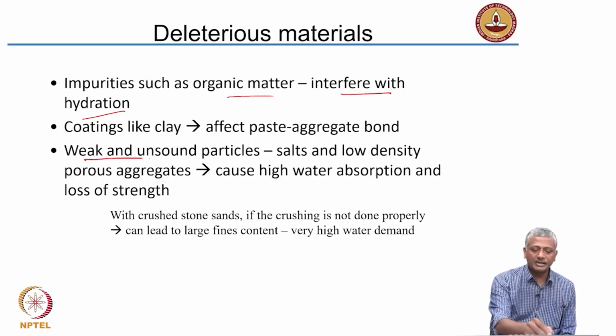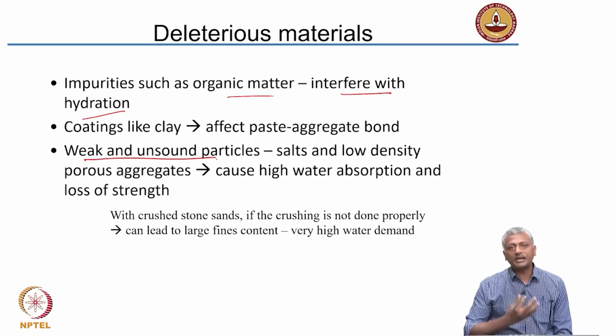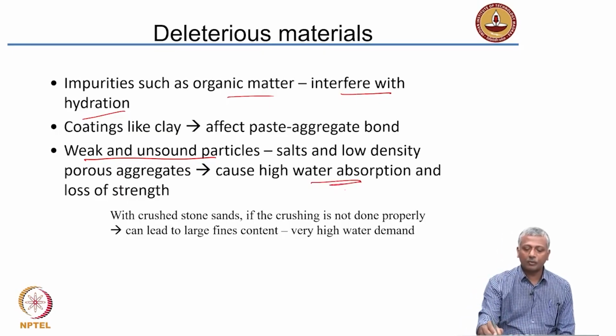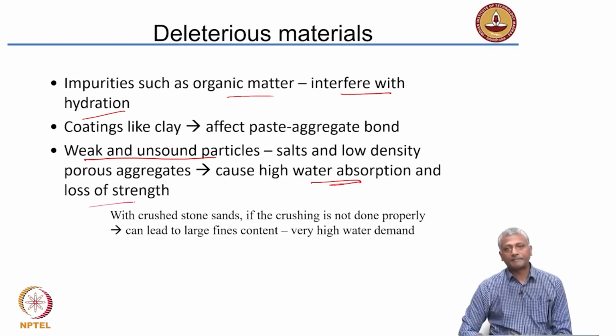The other aspect is weak and unsound particles. As I said, when you collect aggregate from riverbeds, you need to be very careful about finding weak and unsound particles. These can cause very high water absorption and loss of strength.